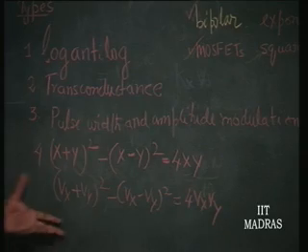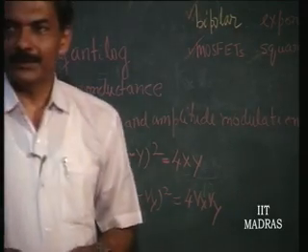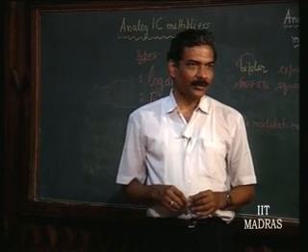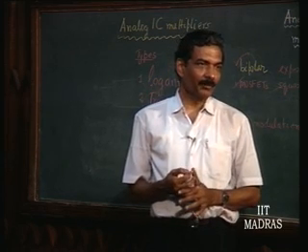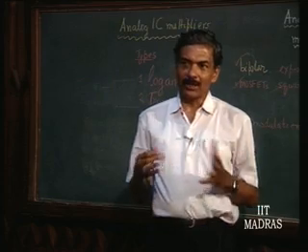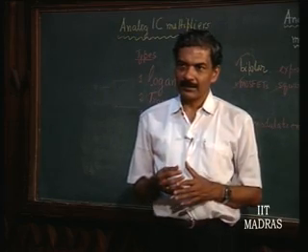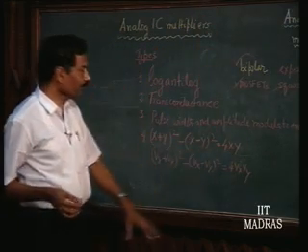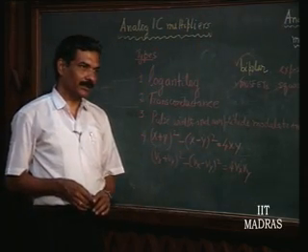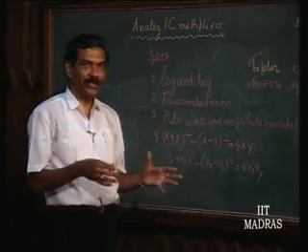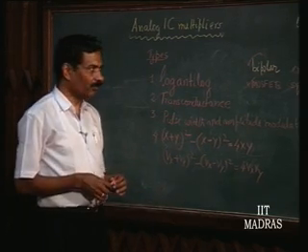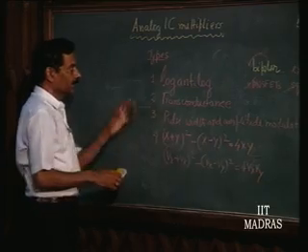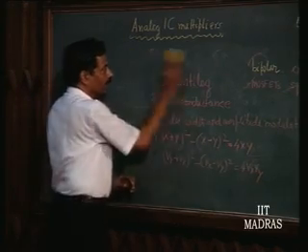So, this is the basic principle of most of the transconductor types, which can be used for multiplication in MOSFET devices, which have large dynamic range. So, we will discuss all these various types of multipliers one after the other, and see how these can be implemented in an IC form. First, let us therefore take this log anti-log multiplier.